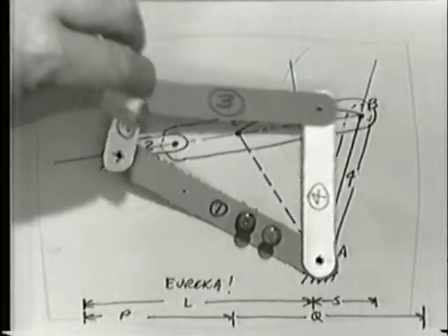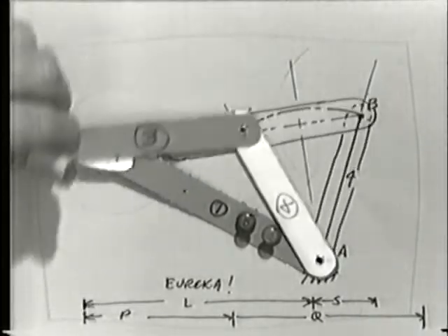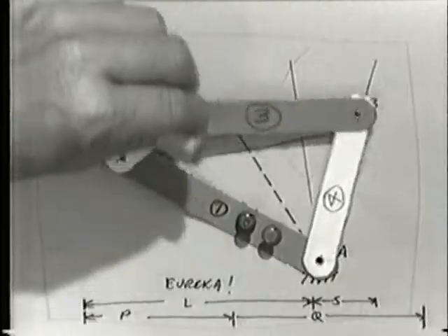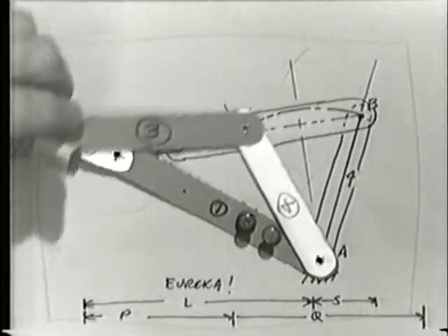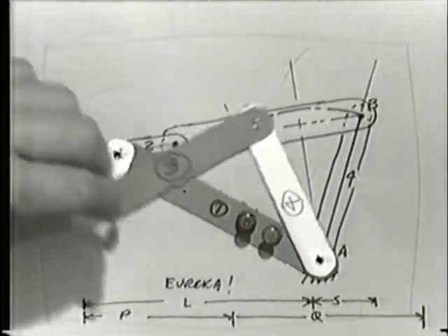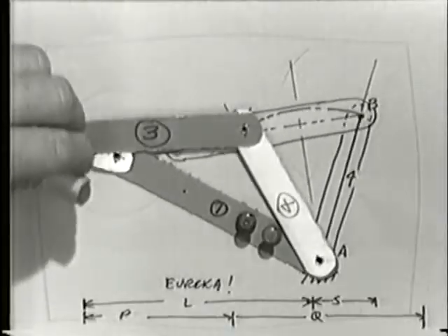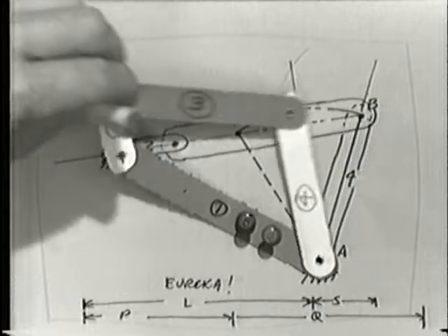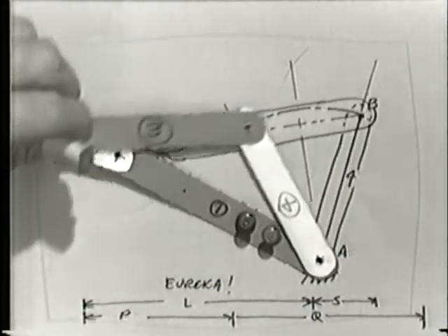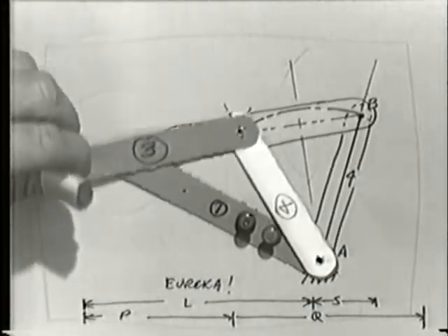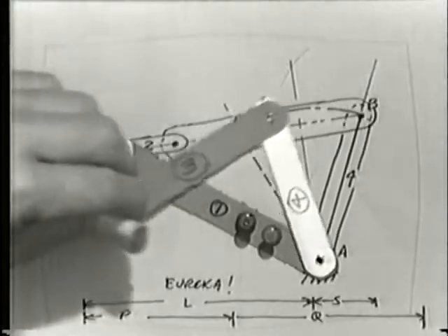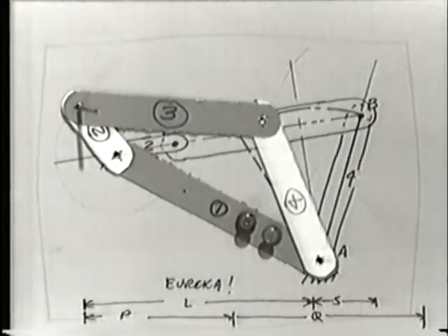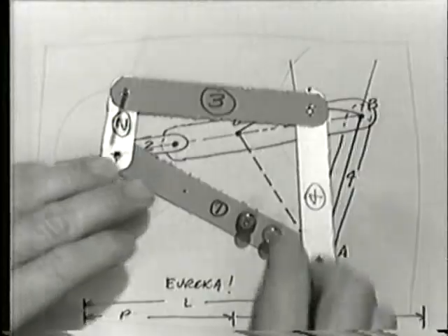And the motor is on, my hand is the motor on link 2, turning it continuously. And if I try to turn that at constant speed, without stubbing the toe here, then I think you can see that link 4 is moving back and forth at about the same time interval. And that's my non-quick return Grashof crank rocker.